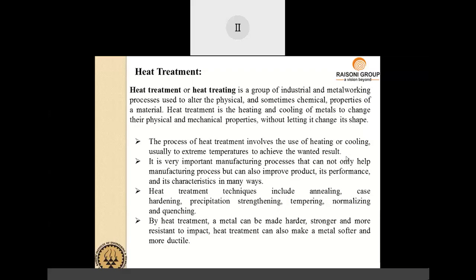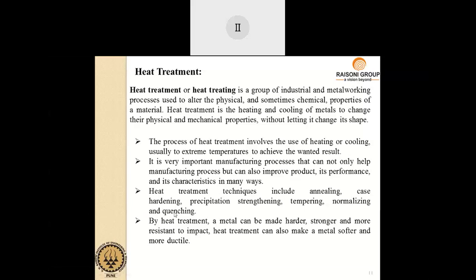Then the microstructure of iron gets converted such that the material becomes very soft and ductile. If you put that iron alloy from 900 degrees Celsius into water, that is called quenching. That same iron rod becomes hard and brittle.